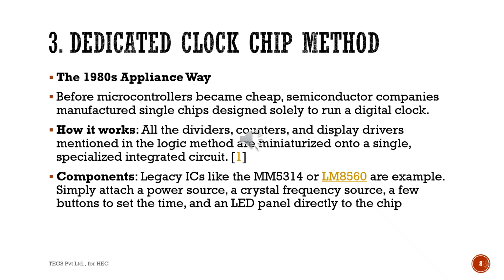Components: legacy ICs like MM5314 or LM8560 are examples. You simply attach the power source, a crystal frequency source, a few buttons to set the time, and a LED panel directly to the chip.